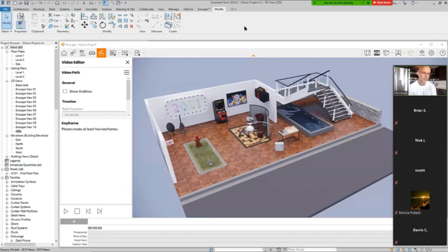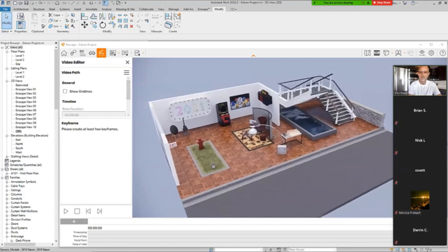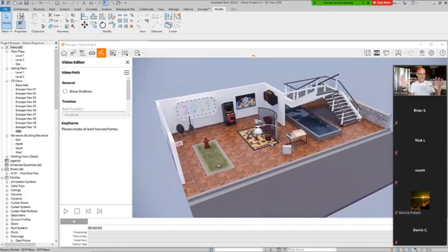So the first thing we're going to do is add keyframes. And to do that, we'll just add the first one. It's all done in first person mode, which is a little bit different than adding keyframes in Revit. So let's say for this initial sequence, we're going to kind of start up high at the left and we're going to move down low to the right. That's going to be our sequence. And we're going to do that initially with 3 cameras.